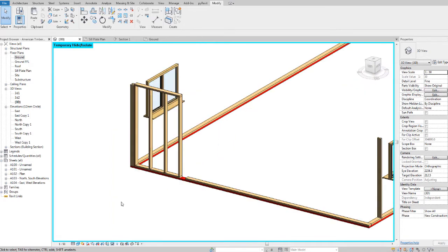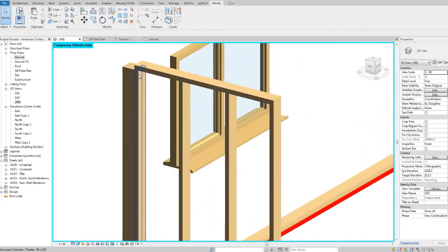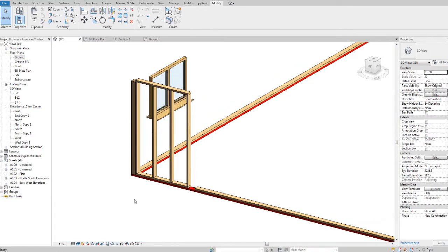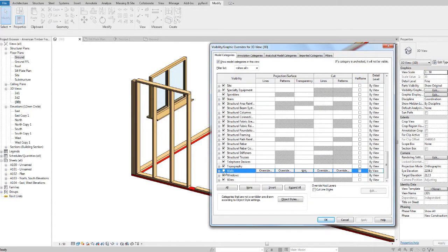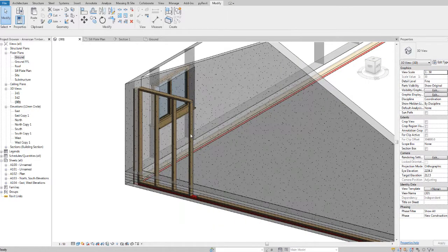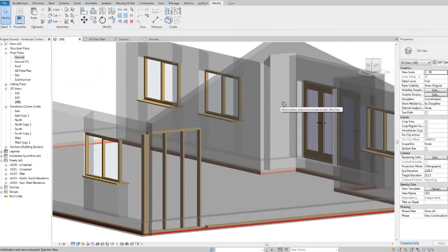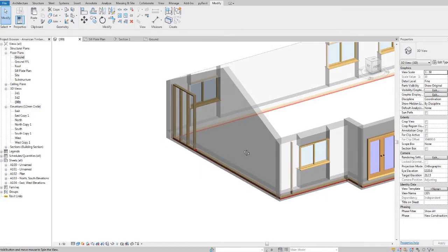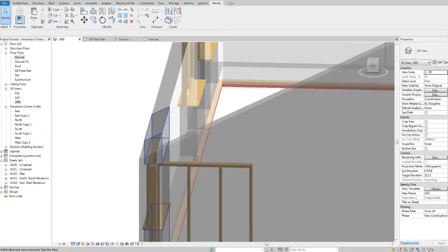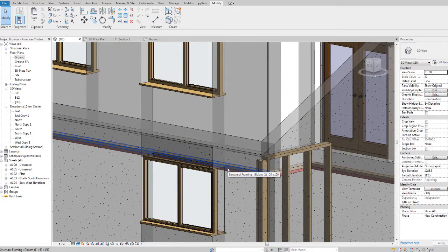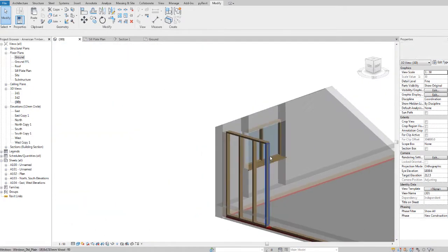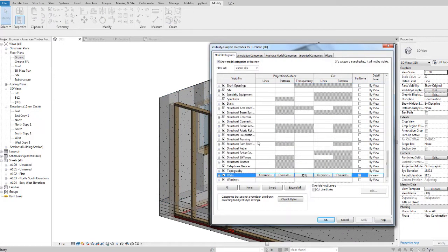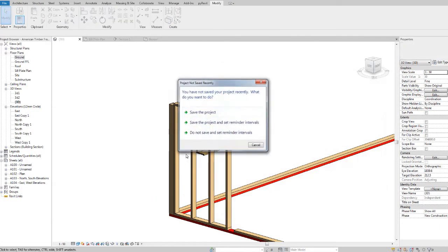I'm just gonna bring the wall back in because I want these frames to be as high as the wall that we've put already. VG, W, bring walls back. I think that's okay. Yeah. If needed, we can edit it later. It's not a problem. So VG, W, get the walls out of here.